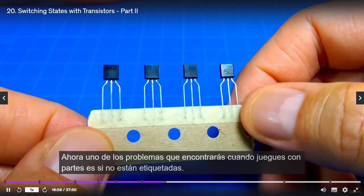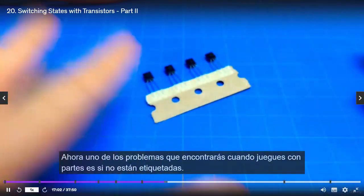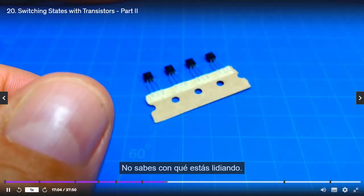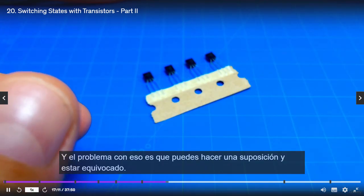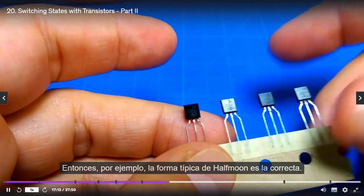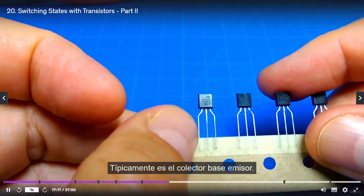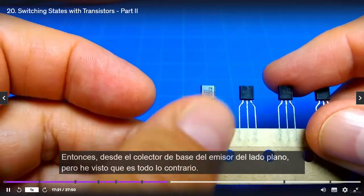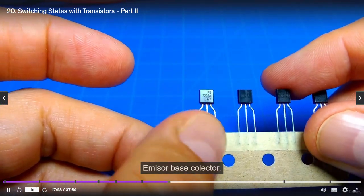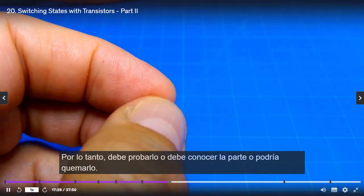So there's no emitter, base, collector marking. One of the problems you're going to find when you're playing with parts is if they're not labeled, you don't know what you're dealing with. And the problem with that is you might make an assumption and you might be wrong. For example, these things are this half moon shape, and typically it's emitter, base, collector from the flat side, but I've seen it be the opposite, collector, base, emitter. So you have to test it, or you have to know the part, or you could potentially burn it out.